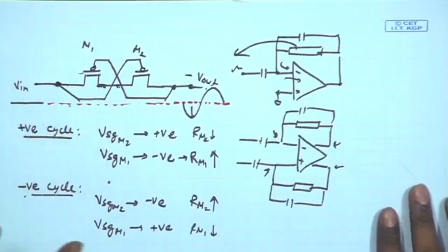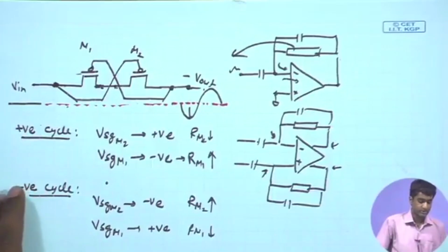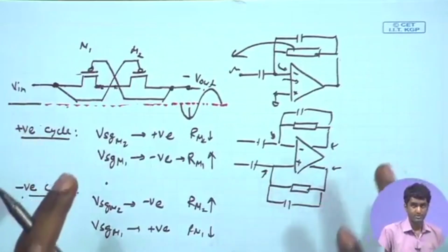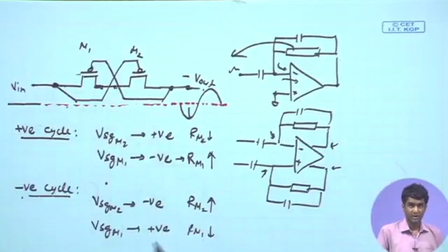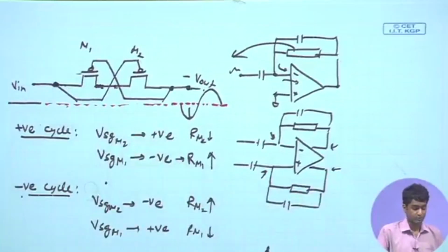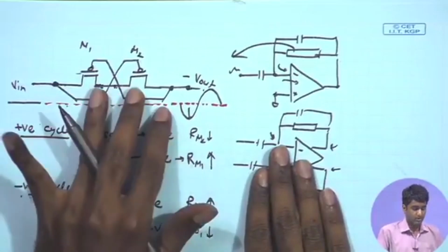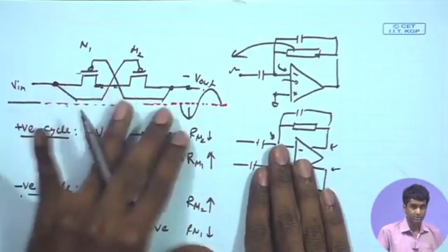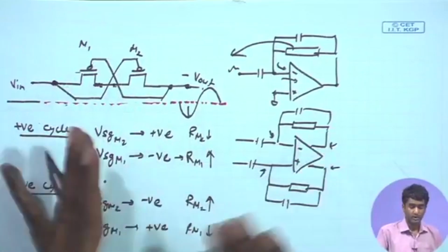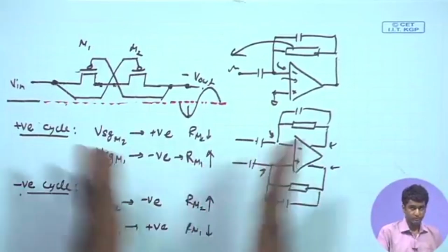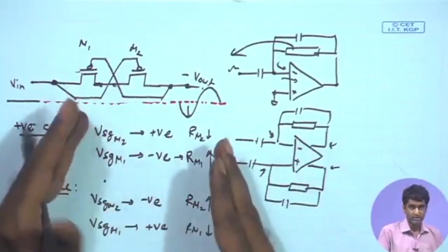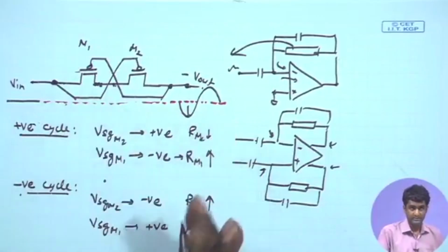Welcome back. As we mentioned, we are going to look into some options for tuning this high value resistor that we just discussed, and the main motivation is that we want to have some options to compensate for the process and temperature variations. So, we will see in simulation exercise also we have options of doing temperature and process simulations. We can run temperatures and different corner simulation to see how much the resistance varies over a given range of temperature, and in general integrated circuits can be exposed to a wide range of temperature, even if it is for a specific application like a neural interface in this case.